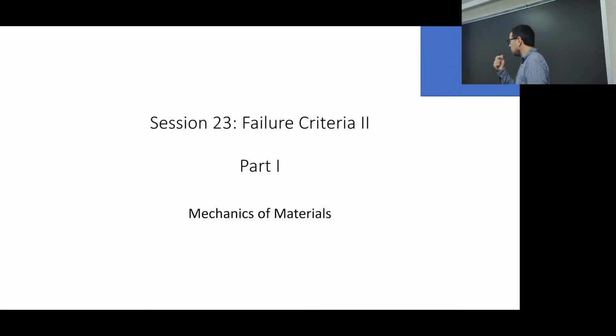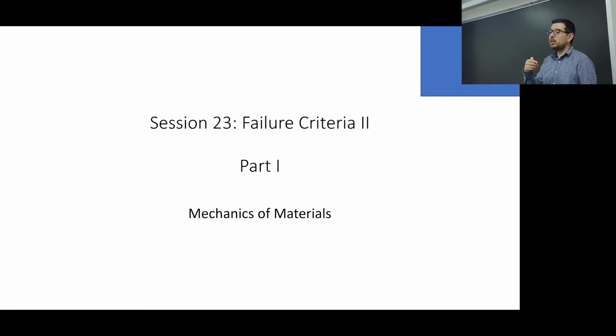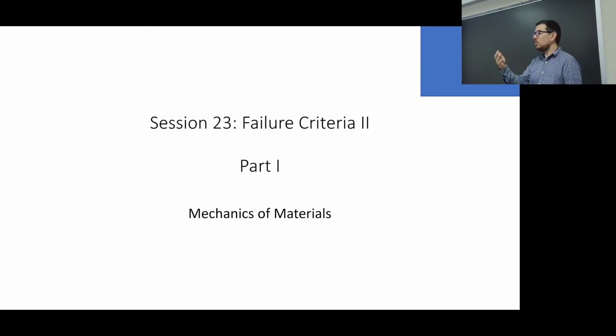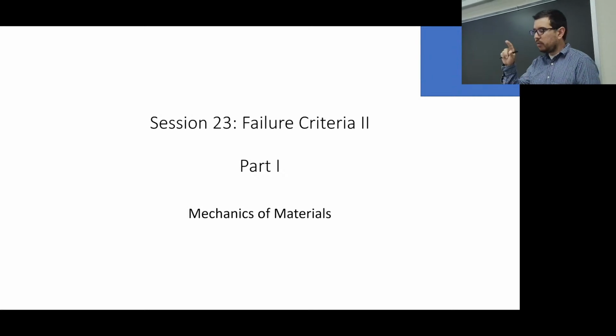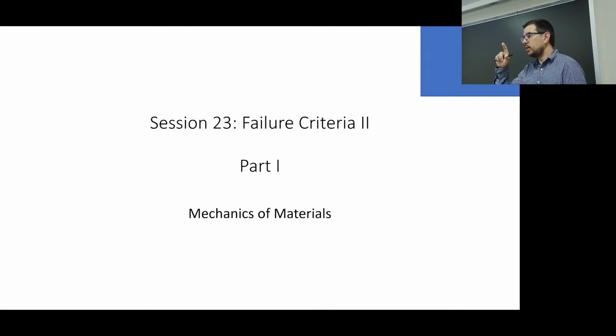We discussed how we can look at what's happening on a Mohr's circle, and then transplant that over to a sigma 1, sigma 2 plot, however you want to call it, and figure out if we're in the box or within the diamond.